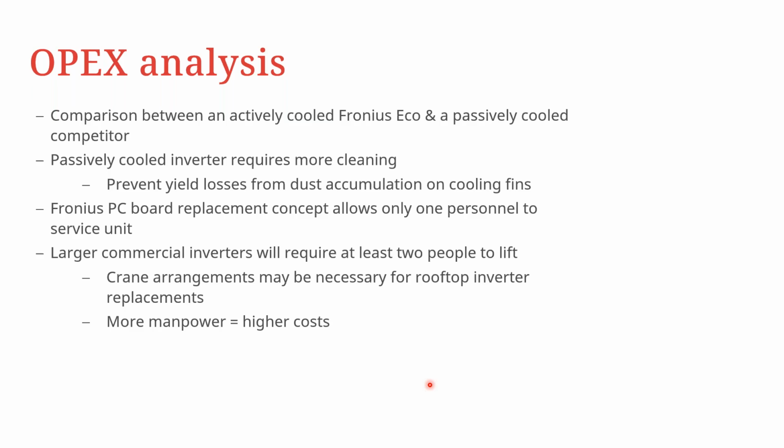Another important aspect as far as the OPEX is concerned: should something go wrong with, for example, a Fronius Snap Inverter, you are able to replace a board as opposed to replacing an entire inverter. And therefore, even in terms of the number of people you need to send to site, with a Fronius Snap Inverter, for board replacement, you can send only one person to site.